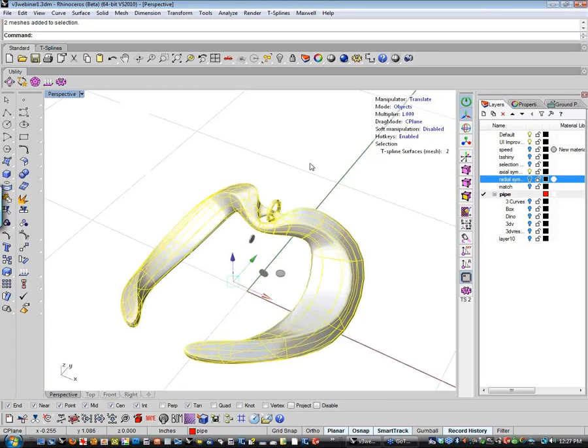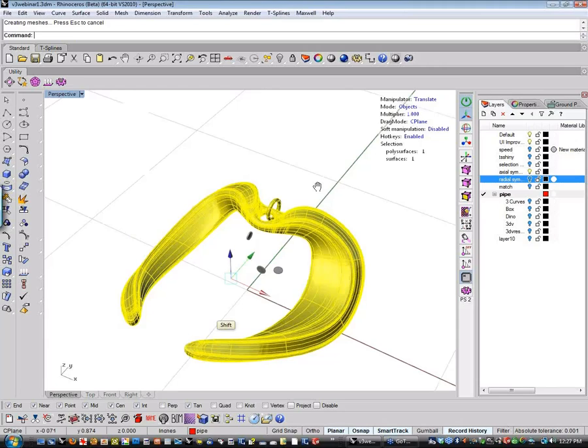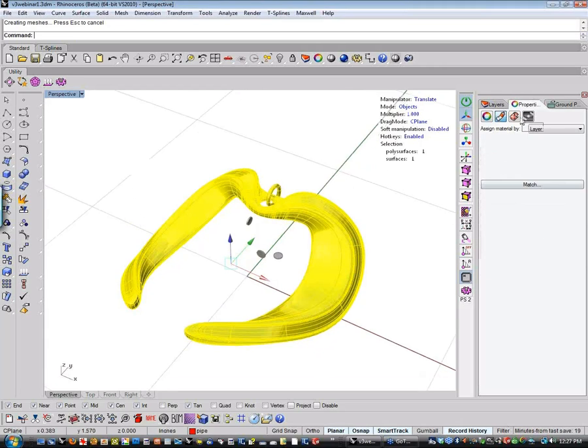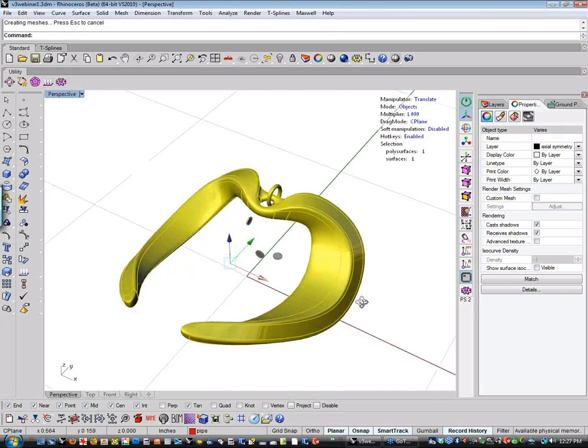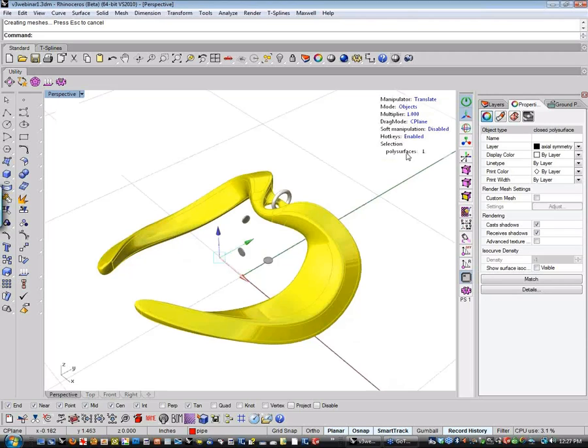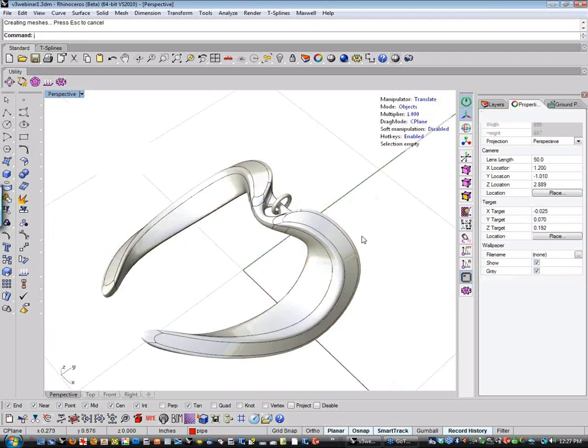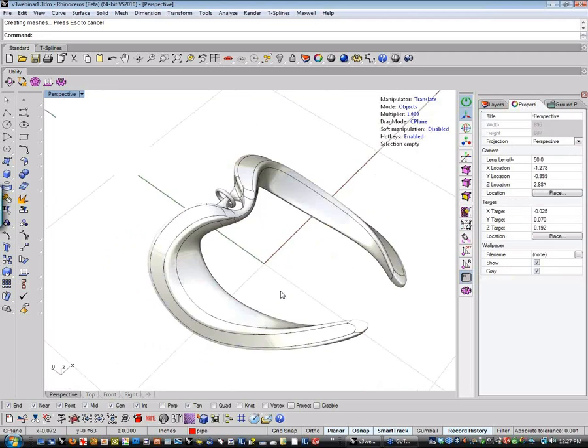It requires the utmost skill of going to the menu and saying convert to Rhino object. I hope everybody caught that. So let me shut off some of the ISO curves here, and you can see this. So now if I pick this, you'll notice that up in my heads-up display it's saying that it's a full-blown poly surface. This is watertight.